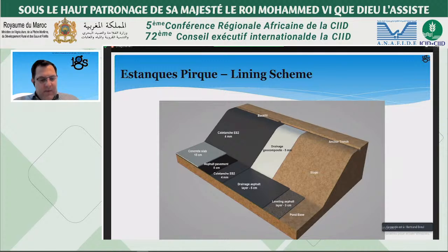The asphalt pavement and the concrete slab allow the mechanical removal of solid deposit on the bottom of the pond without causing damage to the lining system. So the designer chose to use the WG-M to waterproof slope, due to the property of leaving the liner exposed. And again, the fact that it has the NSF 61 certification was a good advantage.